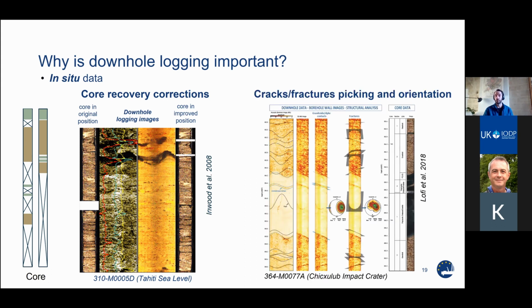Another very powerful use of in situ data is the use of images again. I'm showing images here, but I could show you wiggles as well. But I think images will talk more. You can pick the structures you see in the borehole. They can be fractures, cracks, beddings, and you can orientate them to the magnetic north, meaning you can understand the structural geology and sedimentology within the borehole. And you can also reorientate the cores based on these data sets.